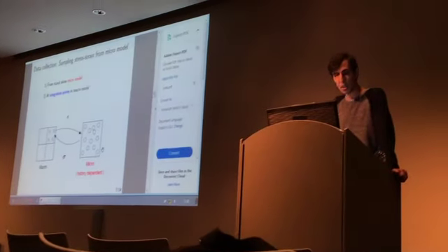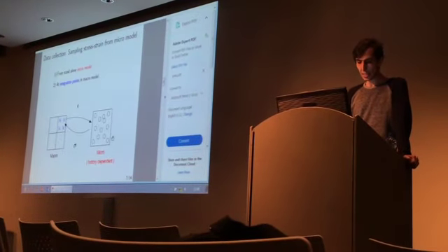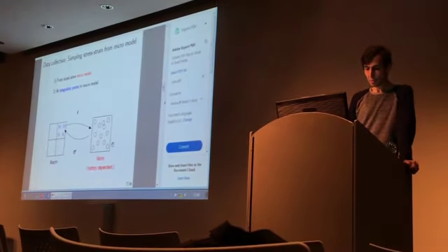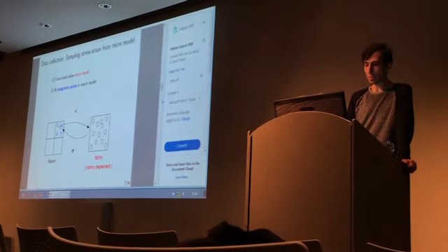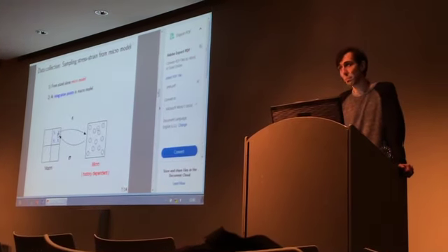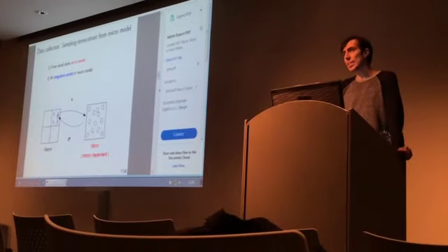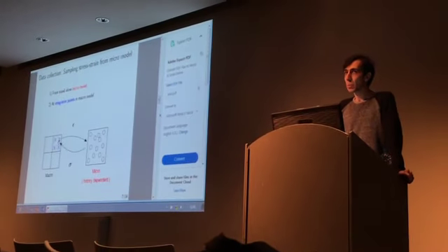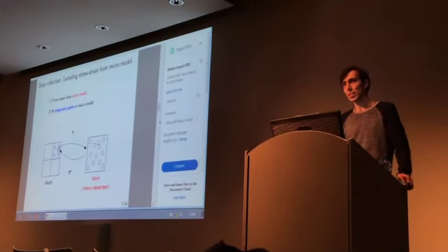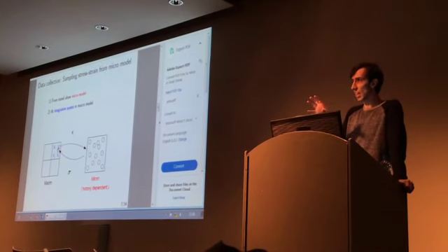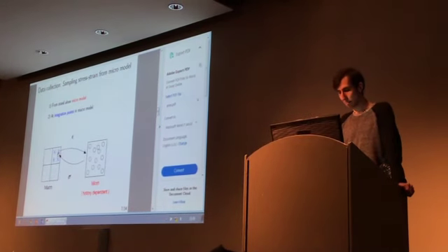impossible. What I suggest to do instead is to collect the samples at the integration points in the macro model, or a set of macro models. In this way, we only sample the space of all possible strain tensors only at the locations that we are actually interested in.